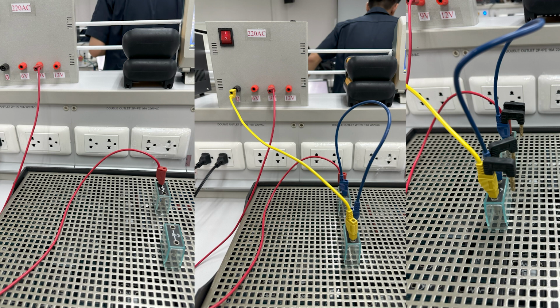So for the first step, we will take a wire and plug it into the AC source of 9 volts, and the end of the wire we will put in the resistor of 1 kilo ohm. Then we also take another wire, put it into the other side of the 1 kilo ohm resistor, and then plug it into the 1 microfarad capacitor on the plus side. And another wire on the minus side goes back into the AC source of 0 volts.